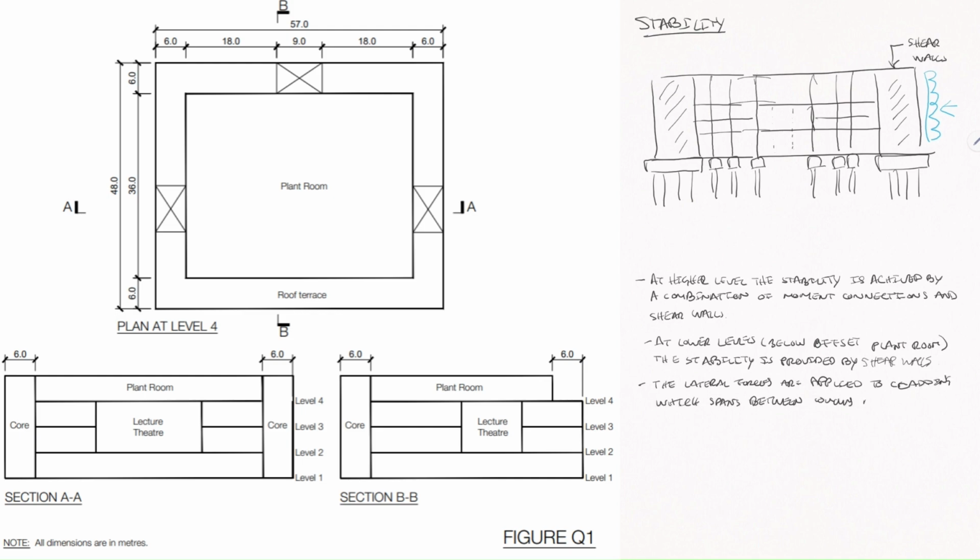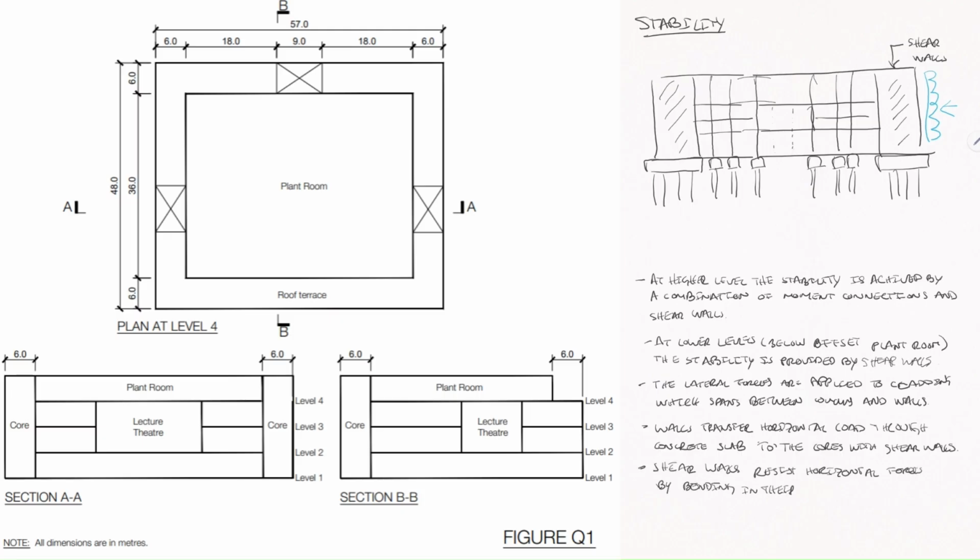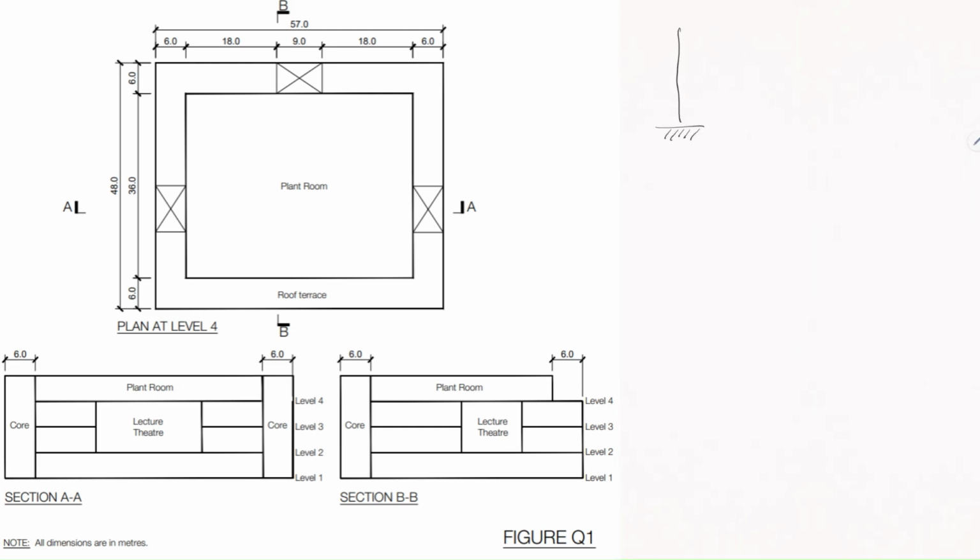And it's the same or similar for the lateral stability. So when you go to wind loads, in this case, because it's a concrete structure, we've got shear walls that are going to be resisting the wind loads. And then I like to show more or less what the behavior of the shear wall would be. I put a very simplified bending moment diagram of the shear walls, which is basically a cantilever column or wall with lateral loads, and I showed the bending moment diagram in my exam.